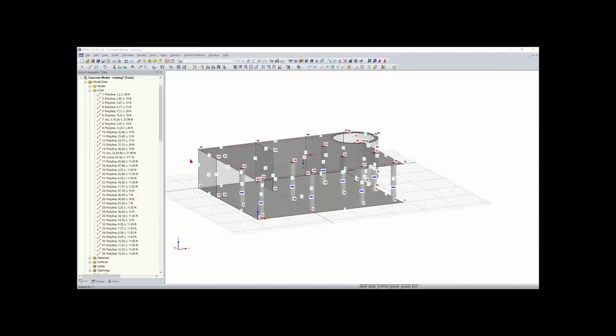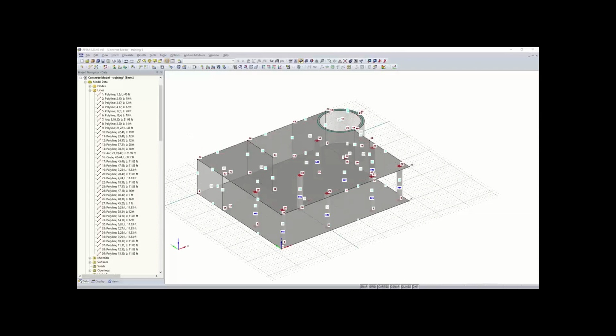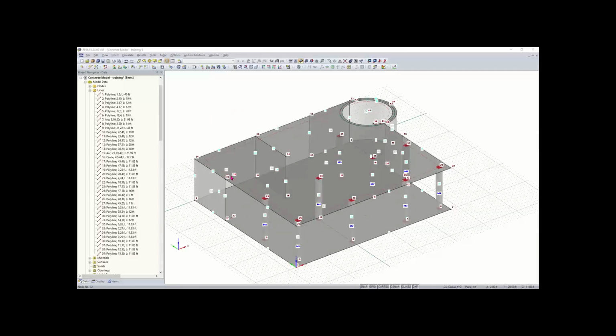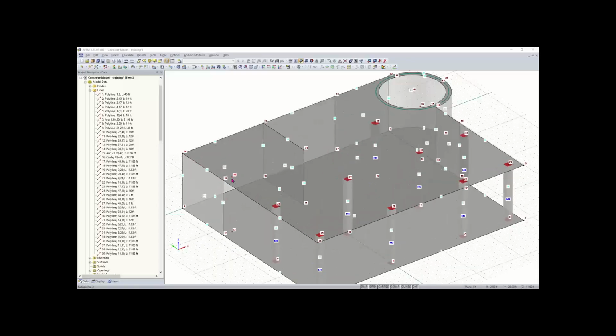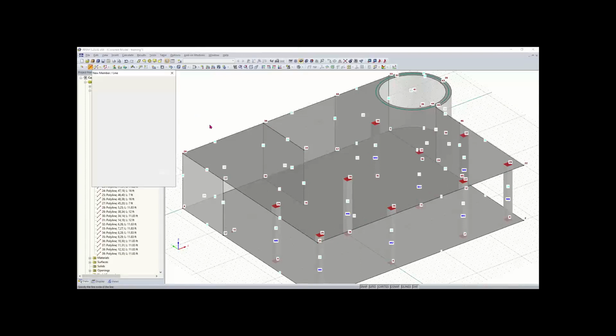And so the last thing we need to do for our model data is just add in this downstand beam. So there will be a downstand beam from the edge of this wall here, node 37, all the way to this column, node 35. This node 33 here is not needed, so I'll select that and delete it. And to add in this beam, I can simply just repeat what I did for the column.